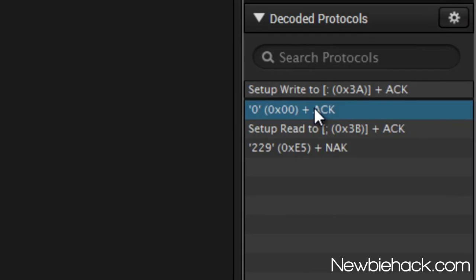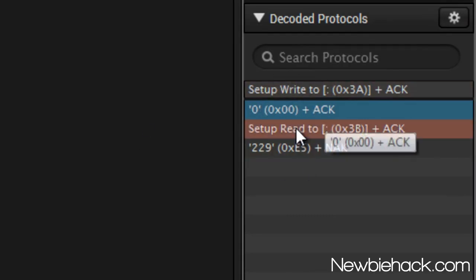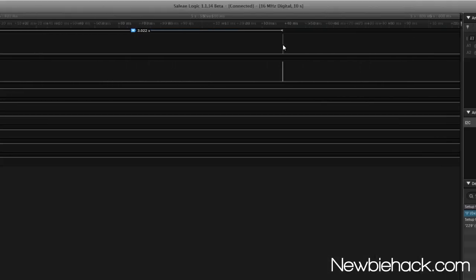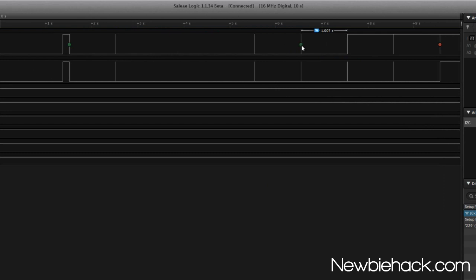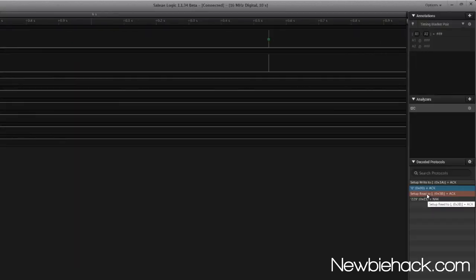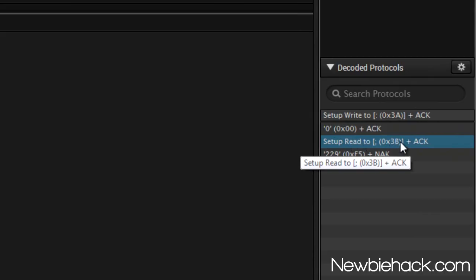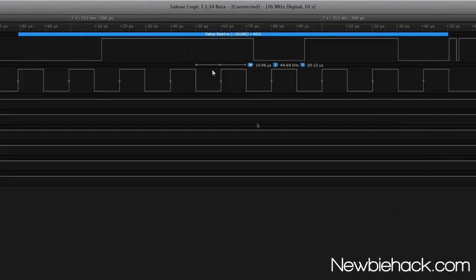And then we did a restart, which we won't see in here. We don't see the start, the restart, or the stop in here. So we can zoom out and take a look at what's next. You can see that the restart is next. So the slave address and read is the next instruction that you see in this location here.